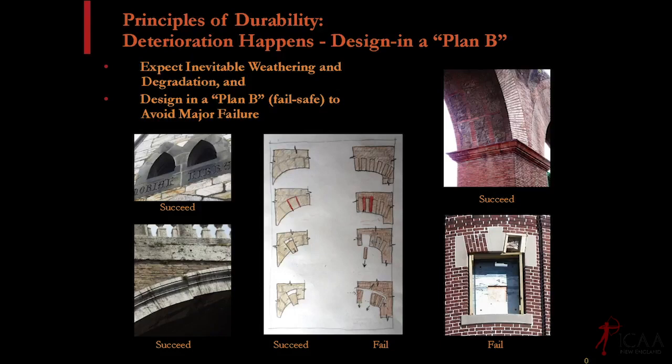He said he'd never seen brick fall out of an arch in the 30 years or so he had been doing masonry. And I think what was happening here was they had a very wide mortar joint, and the brick were not cut to wedge shapes. So when you lost the mortar, something like this, that brick was able to drop straight out, and then all of a sudden you had localized instabilities around it, and those brick were able to start dropping out too. And he had shored it with 2-bys by the time I got there, before a progressive collapse occurred.